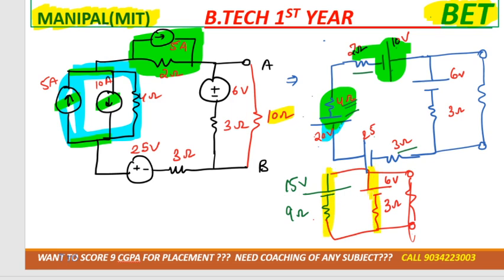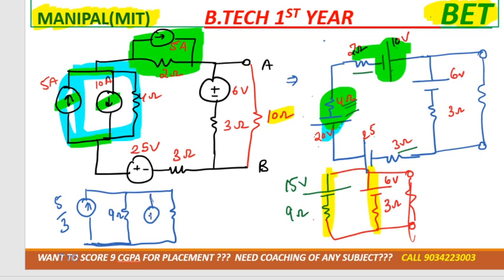So now again we need to convert this voltage source into the current source. Correct? So it would be 9 ohm as I told you, as it is, and that would be 15 by 9. 15 by 9 would be 5 by 3 ampere. Similarly, this 3 ohm will be as it is, and the current source would be V by R, that is 6 by 3, that would be 2 ampere. Correct? So if we solve it further, 5 by 3 and 2 ampere are in the same direction. Correct? And 9 ohm and 3 ohm are connected in opposite.